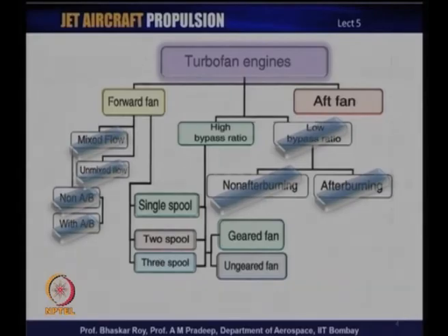We will be talking about the forward fan, the aft fan, and of course, the high bypass ratio fans, which come in single spool, 2 spool, and 3 spool, and then of course, we will have a look at the geared fan, which is a special variety of large turbofan engines. So, these are the ones which we will be looking at today in some detail and try to look at their differences, how they function, what their mechanical details are and exactly how they compare with each other.